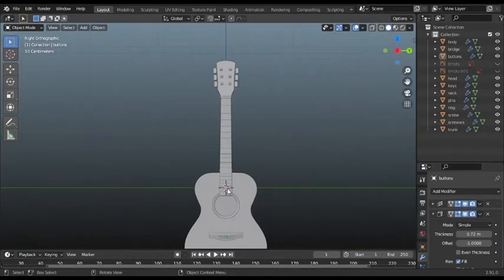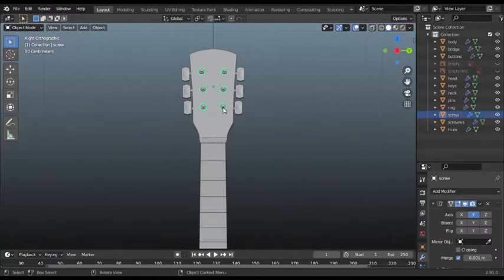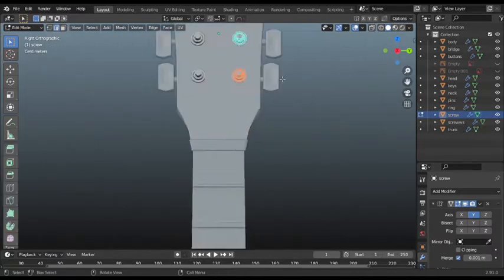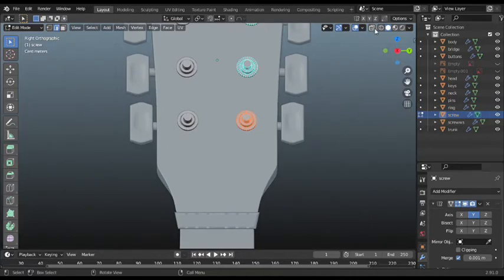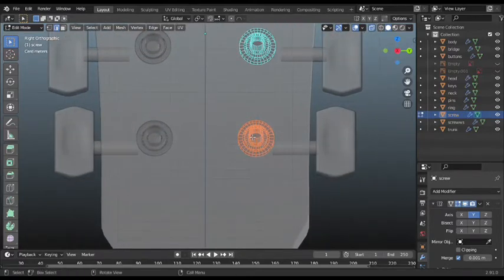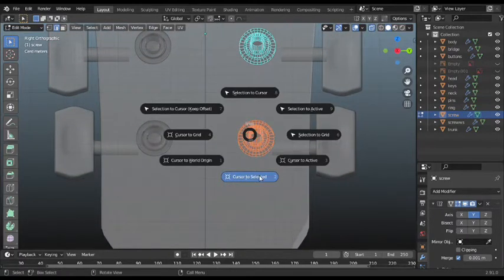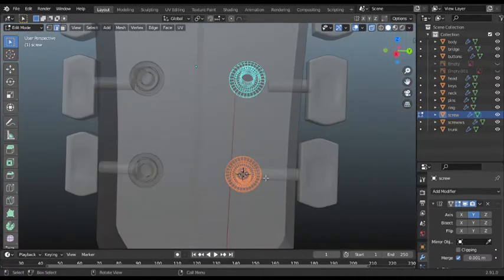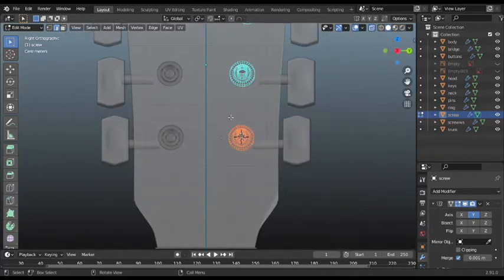Now the purpose of this 3D cursor is it is the gateway of the objects, not only objects, anything we add in, it's the gateway in our world origin. You'll get to see with just a simple example. All I'm gonna do is select this screw set, then tab into edit mode and I'll zoom in. I'll enable X-ray and select a complete ring, any one of them. Then I'll press Shift S and cursor to selected. You'll observe that the cursor will be placed in the center of the screw. So this is gonna help me to add in the parts of the wire that I'll be needing.